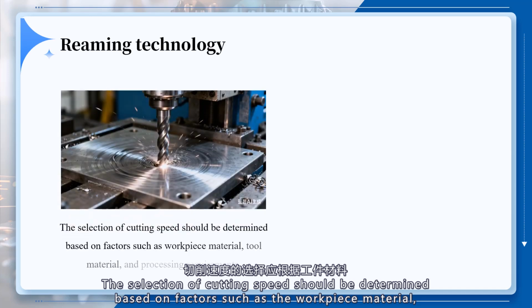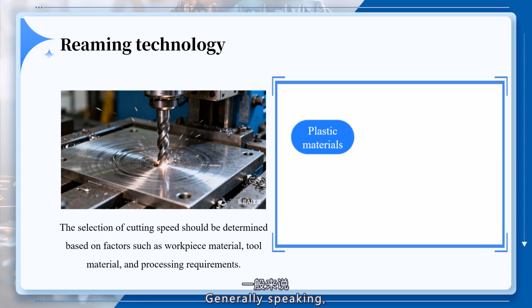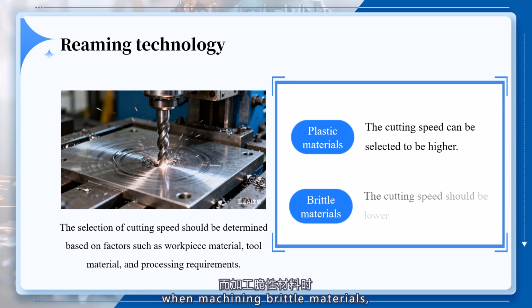The selection of cutting speed should be determined based on factors such as the workpiece material, tool material, and processing requirements. Generally speaking, when machining ductile materials, a higher cutting speed can be chosen. When machining brittle materials, the cutting speed should be lower. Feed rate.